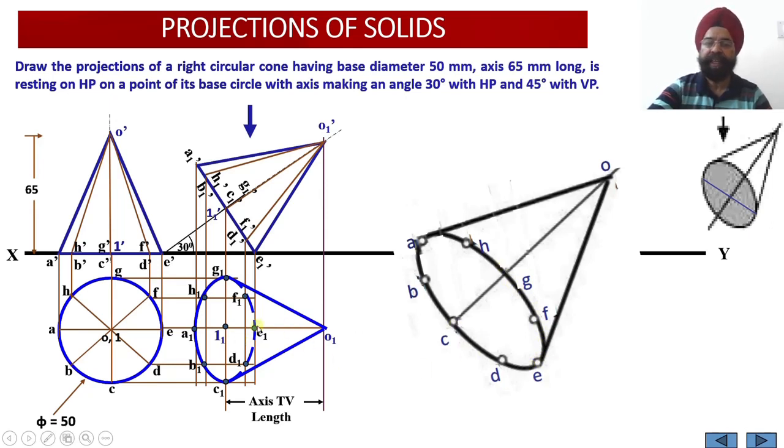So the simple fundamental which was used for the ellipse in the case of prisms and pyramids is not applicable in the case of cone. In case of cone, half of the semicircular portion will be visible, and the remaining half will be dotted. It's not that since this is the farthest point, only this semicircular portion should be dotted. No, it is the entire semicircular portion which will be dotted. That is why I have shown it separately with the help of a bigger model.